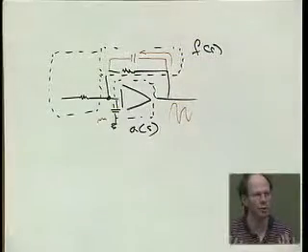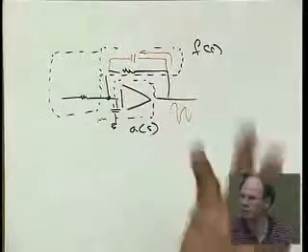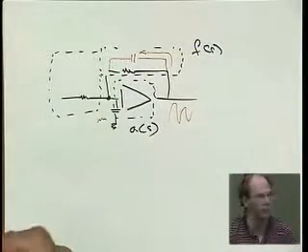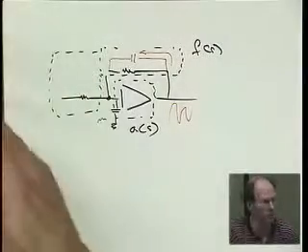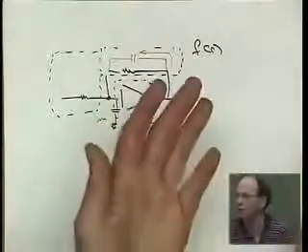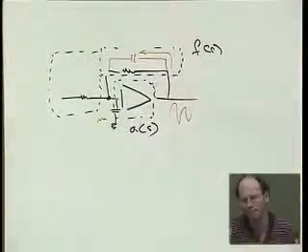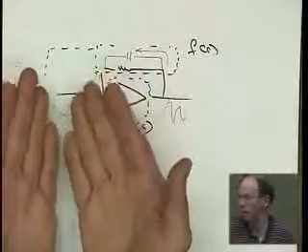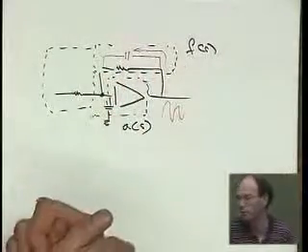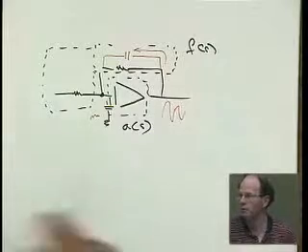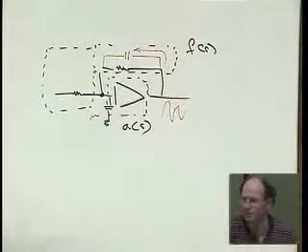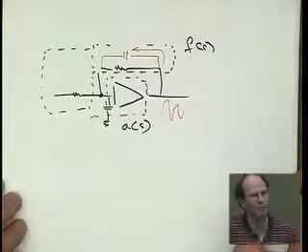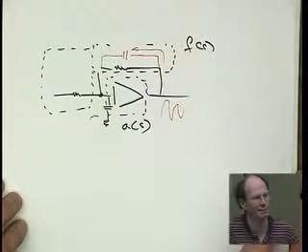There is only one loop gain around the loop, and it determines the stability of the circuit, and that's the loop gain we want. If we use an approximation, we may have good reasons why we use that approximation, but then we get an approximation to that real thing, and there is only one real thing. For example, the Gray and Meyer text calls one thing return ratio, the other one it calls loop gain. Well, they really are the same thing. At least they are approximations of the same thing. Other questions? So you see, even in this hot room, some things get me completely worked up.